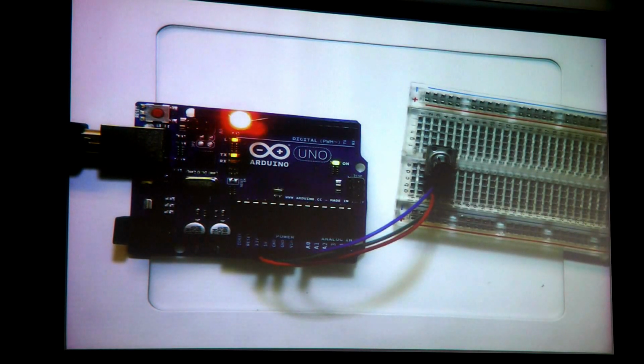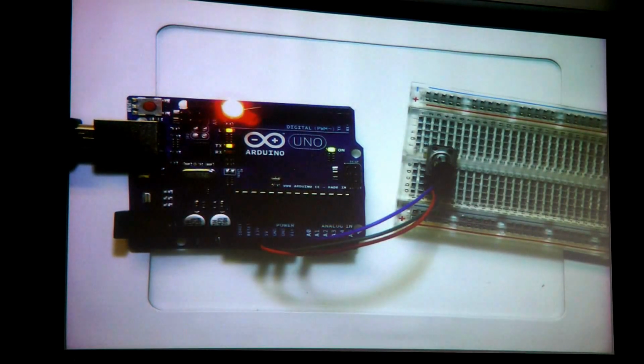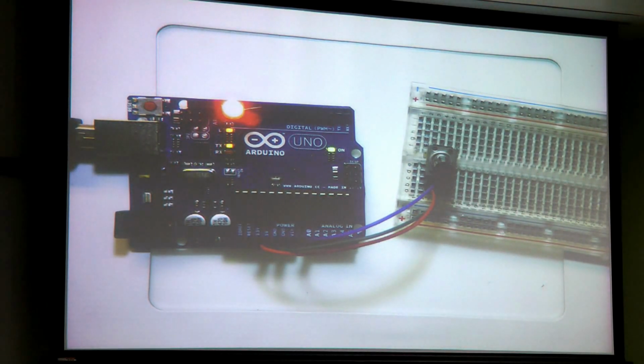analog write command. Because the way Arduino is, it's actually a bunch of little macros that do things for you to make programming easier. The way the programming works for the Atmel chip is you have to write a whole port, which makes it hard if you have some pins on, you need to OR it, or if you want to turn it off, I think you need to do an XOR or something.